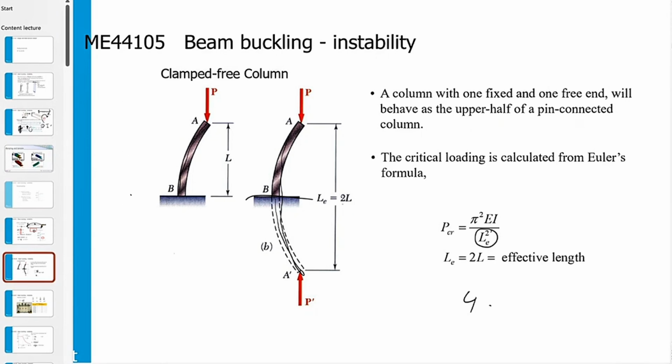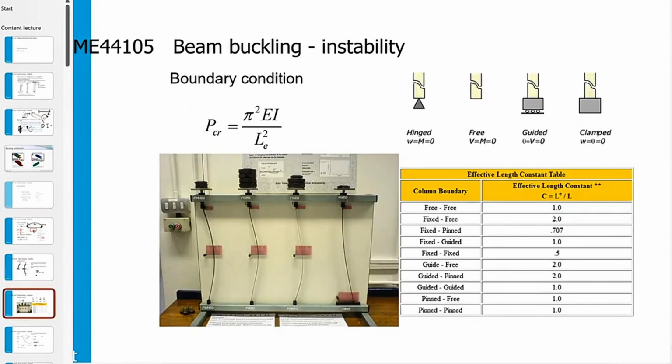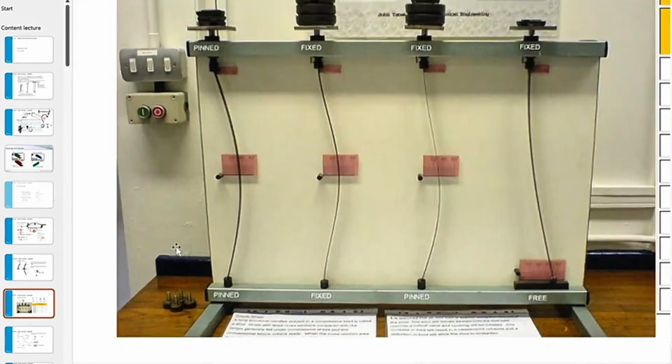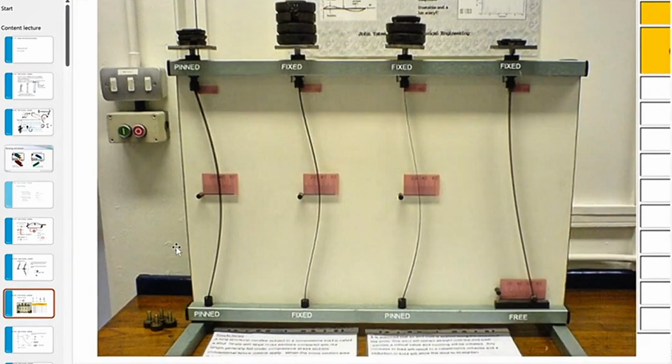This is a very nice engineering concept, but there was somebody on, I think it was on Reddit, and I'm not sure if it's still there, who thought, well, it's nice to have these buckling values, but seeing is believing. I'll just make an example. So he made the standard beam buckling, where you can see the loads here. This is pinned and pinned, so it can rotate both at the bottom and at the top. And then he made different effects.